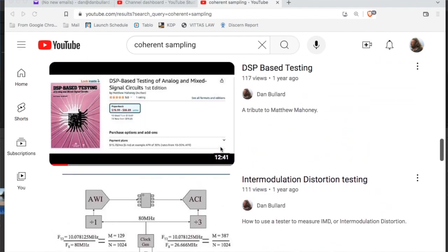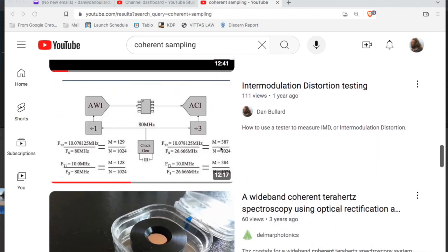Coherent sampling is super important. Without coherent sampling, the FFT is an approximation. That's what the people at Tektronix said. It's just a button on a scope. But with coherent sampling, you can resolve every picovolt of energy from a waveform or from any other thing. If you do modal analysis like my buddy Bruce Polo at Genred, you could look at vibrations that are too small to be noticed by anything. So it's really cool. Coherent sampling is wonderful.